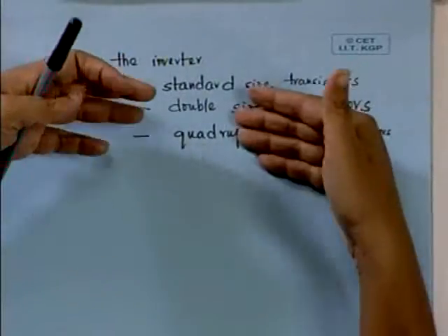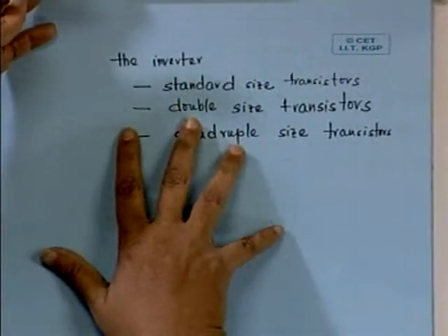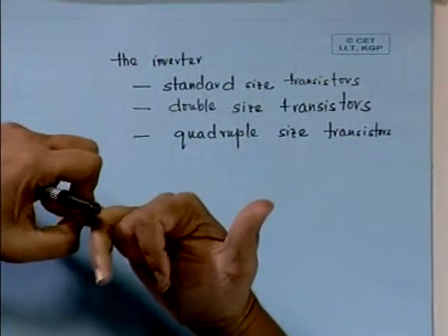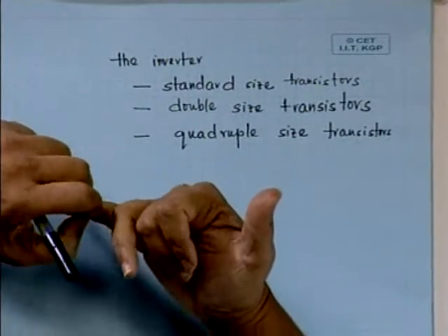These are the basic elements, the inverter, the different gates, the different cells, and the three criteria I have told, speed, power and area, and how to optimize these three things. Sometimes it is provided by some vendor, sometimes the designer can build his own library. That is why this semi-custom style or standard cell library is very important nowadays.